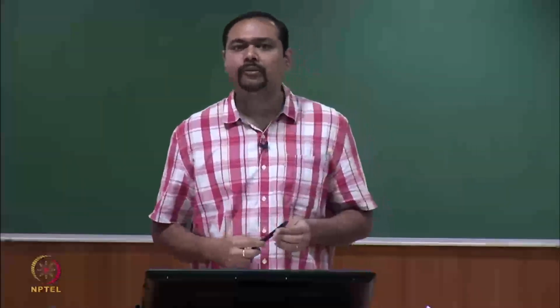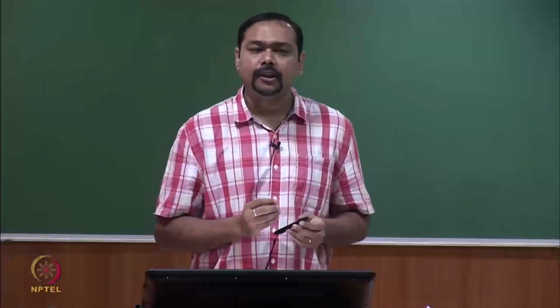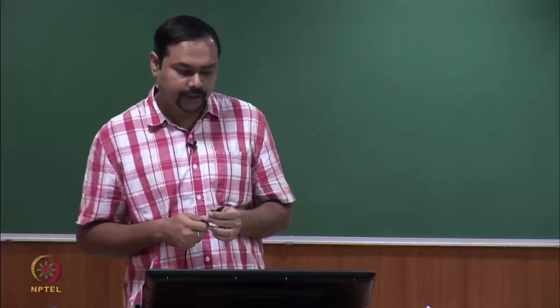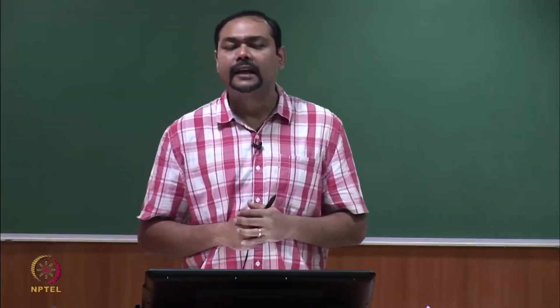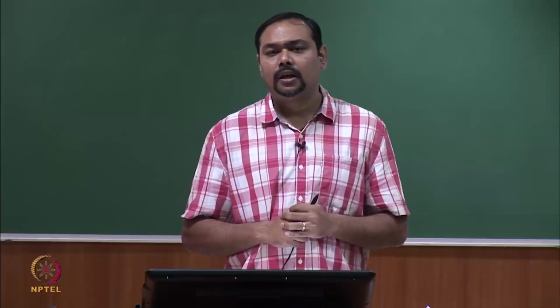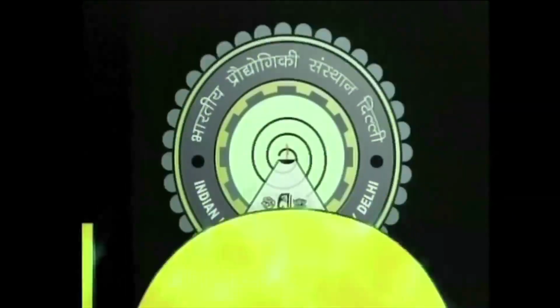We are not going to talk about it, but this discussion tells you that there are many possibilities by using this degree of freedom of point O, because point O is the converter's neutral point and it is completely floating. It gives you a degree of freedom. So, we will conclude the discussion on cascaded H-bridge here.